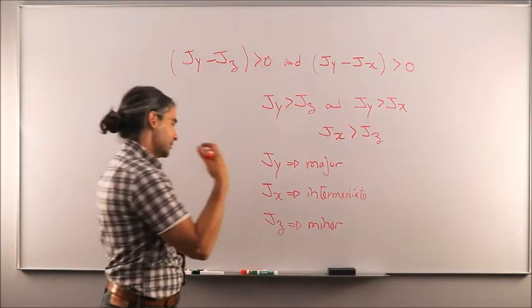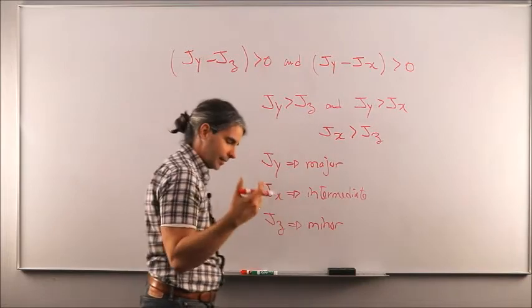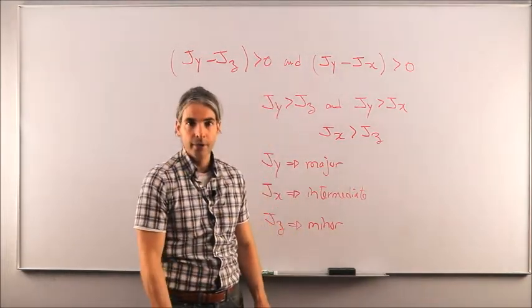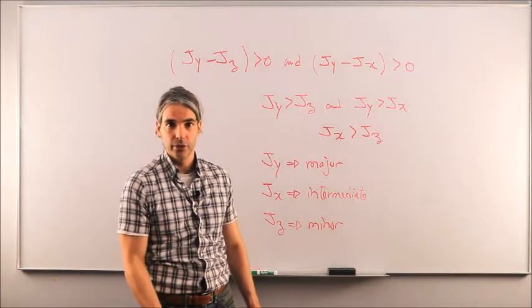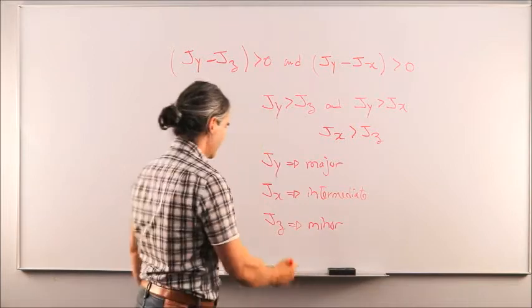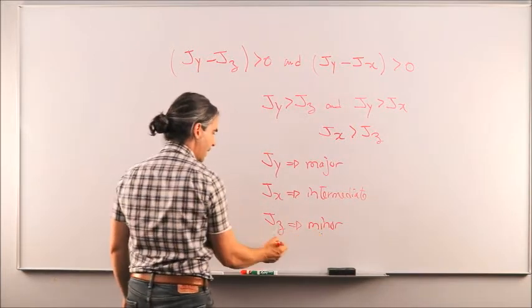So that makes a lot of sense because I had begun this section by saying that gravity gradient would want to naturally align the minor axis of rotation of the body fixed reference frame towards the Earth. And guess what? The minor axis happens to be Jz.